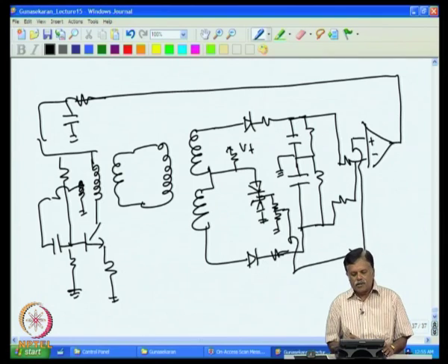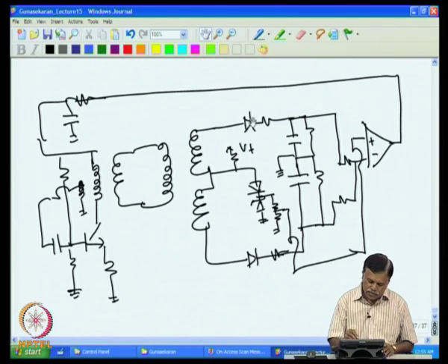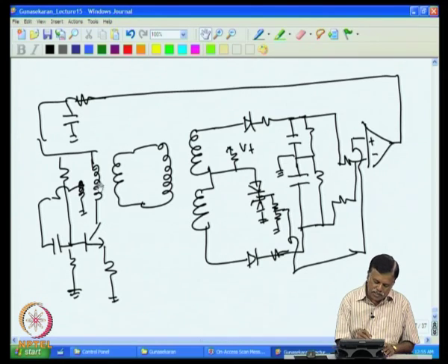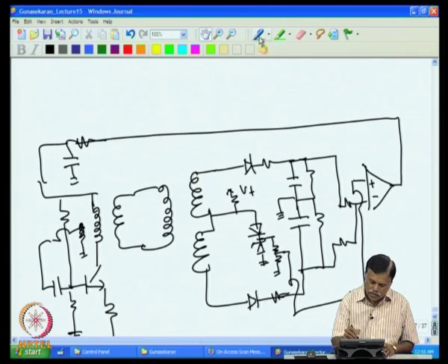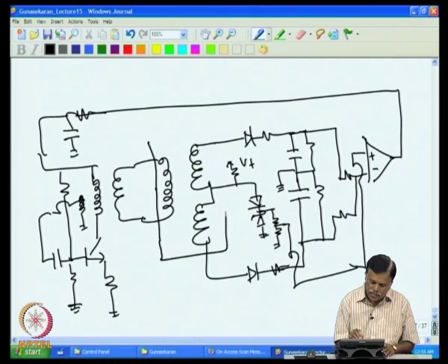So that solves both the problems, that is we have now solved the temperature problem of the rectifier diodes, and then we also solved, by giving the feedback and maintaining V1 plus V2 constant, the temperature induced error due to the resistance drift of the LVDT, because this is the LVDT.